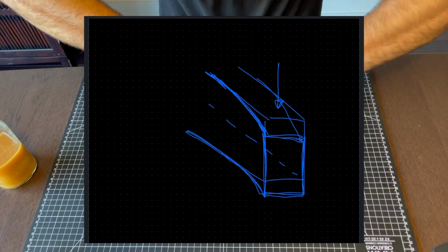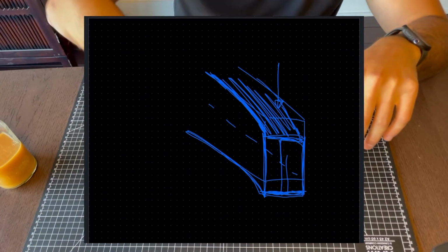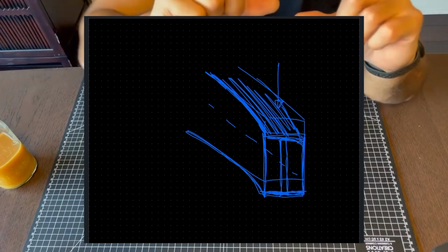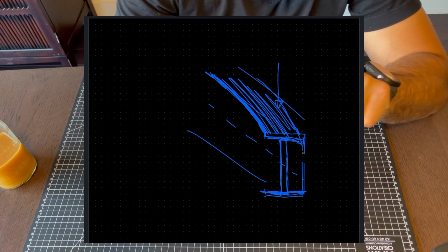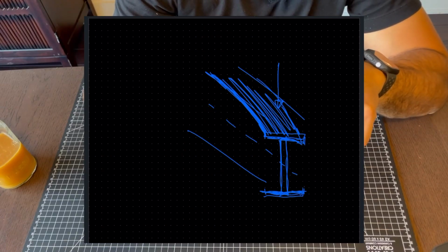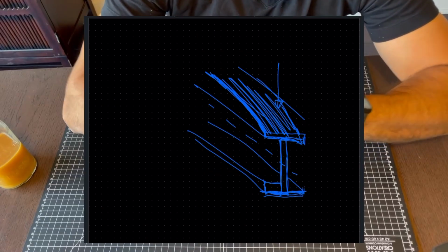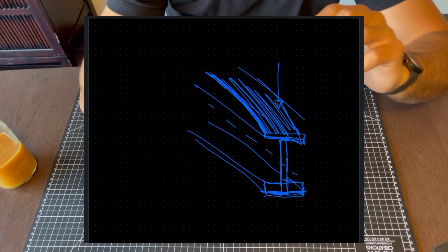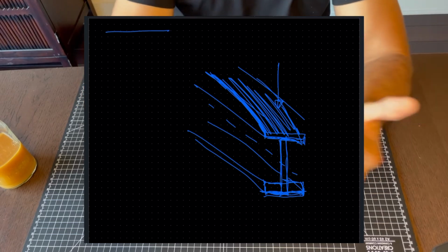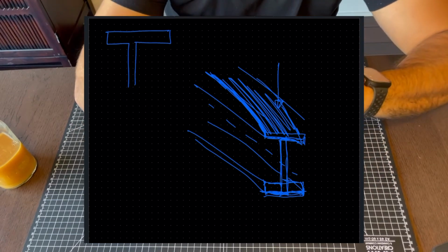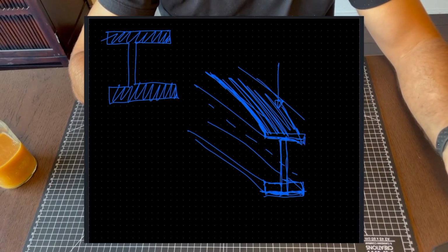When I'm bending something, the stress isn't the same across the entire cross section. If we cut down the middle, what we're going to see is a lot of compression, pressing on the top, and a lot of tension at the bottom, or vice versa. So let's say, for example, I'm bending it this way. This top part, all the very tiny blocks that we can imagine are going to be pulling away from each other. And on the bottom, they're all going to be pushing into each other. We can see in this diagram what it looks like.